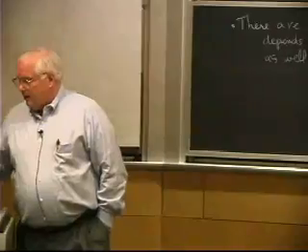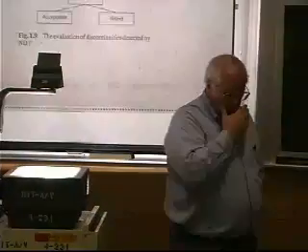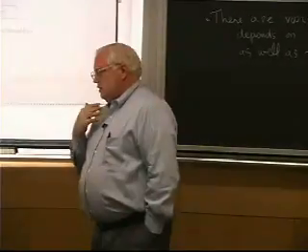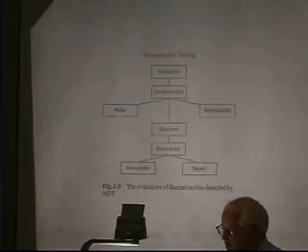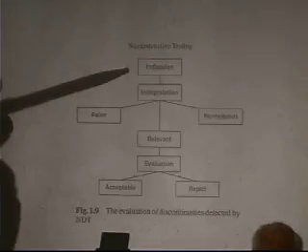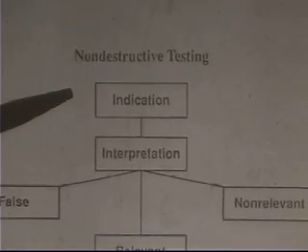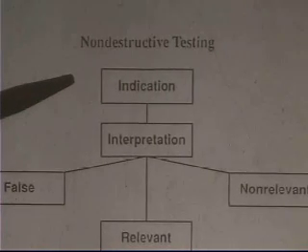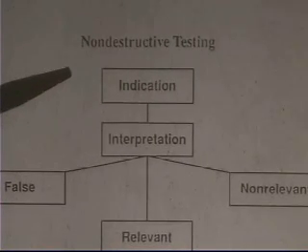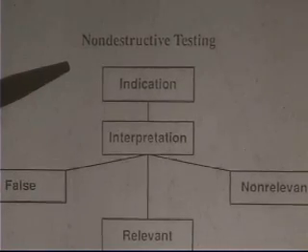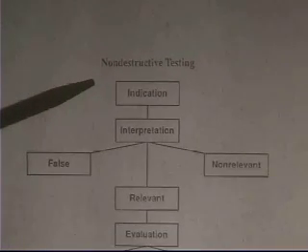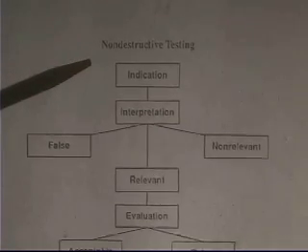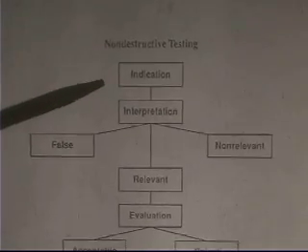So now, if we get into trying to understand what is a defect and what is a flaw, it turns out the non-destructive test folks have gotten fairly precise in their terminology. They don't call it a flaw, because depending on what you're doing, it's just this change of gray, or it's a little blip on an oscilloscope in ultrasonic. In X-rays, it's a change of gray on the X-ray. In ultrasonic, it's a blip on an oscilloscope. In penetrant inspection, it's a little bit of red coloring on a white background. So it's not really a flaw, it's just what they call an indication.